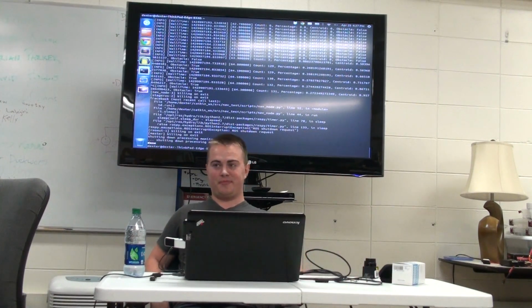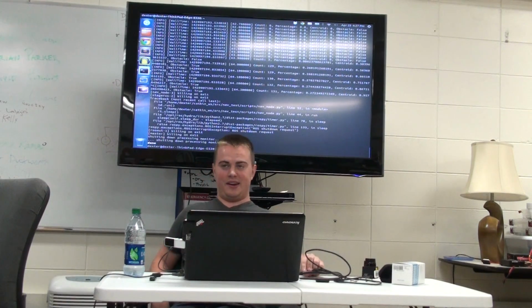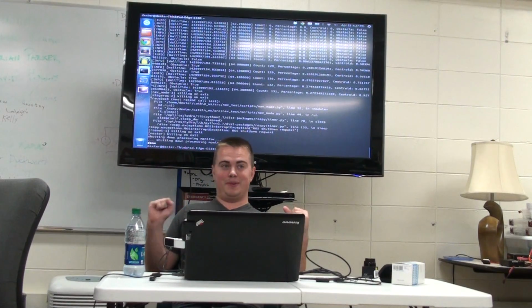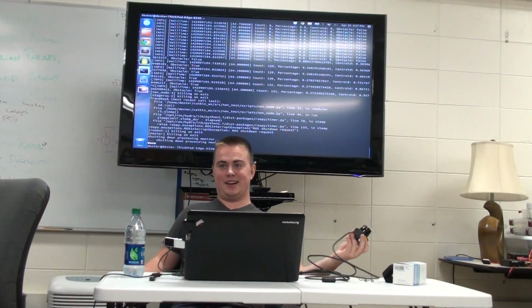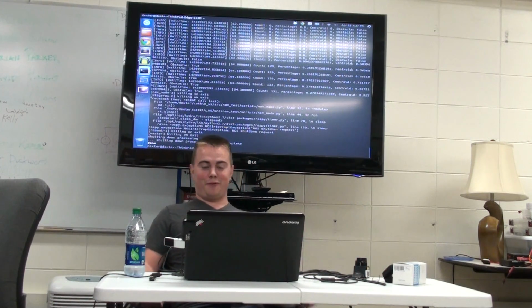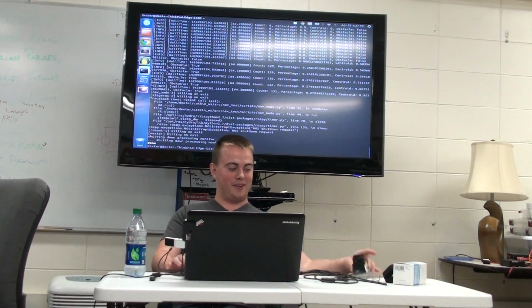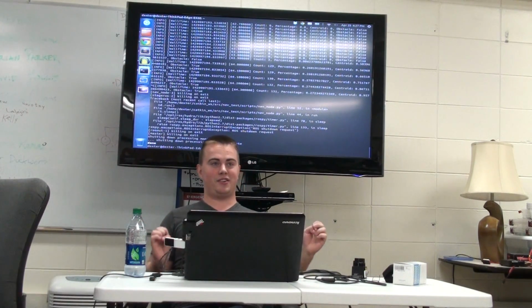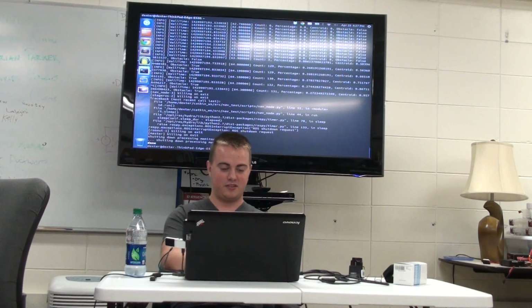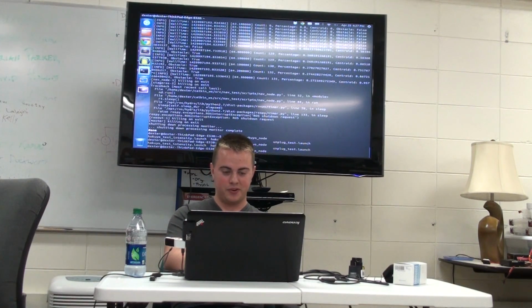So this is plugged in to my computer, and the nice thing about ROS is that there are drivers for everything already. So you don't have to spend all day trying to convert laser data from serial to a ROS message because someone conveniently made it for you. For example, to launch this, I have downloaded a package called hokuyo_node, which is the brand of this laser. So I'm going to do roslaunch hokuyo_node, and then let's see what the possible options are. I want to do hokuyo_test.